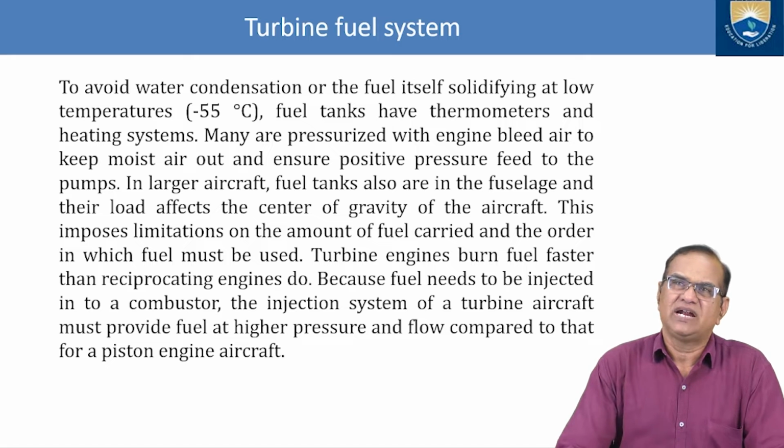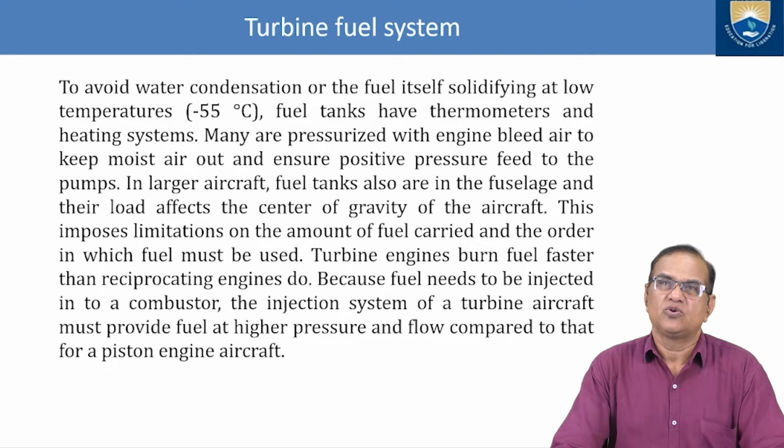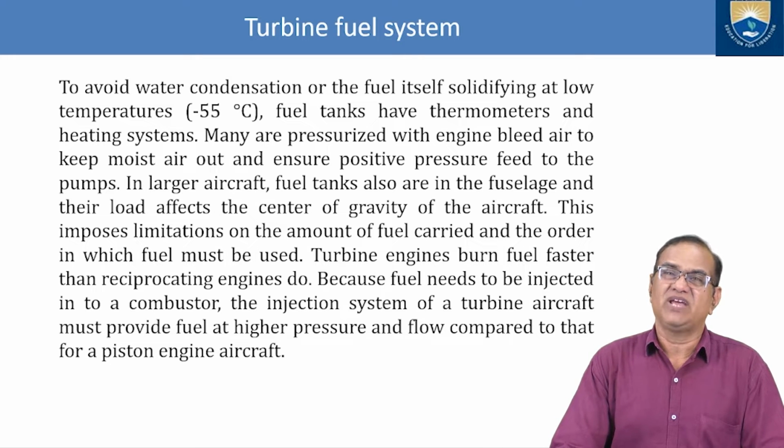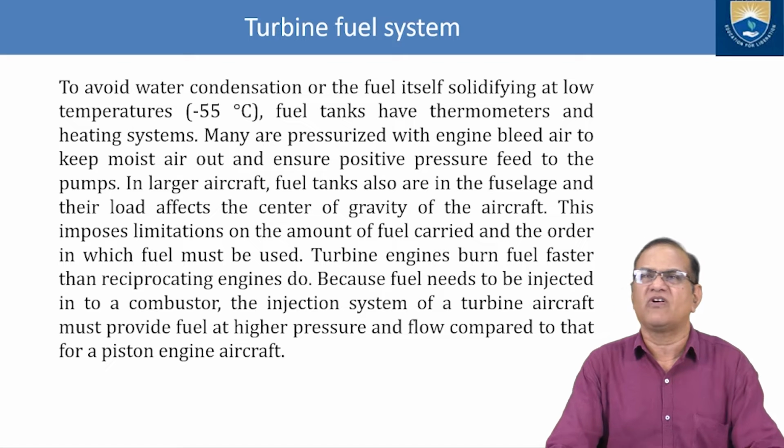Now I will talk about the turbine fuel system. Between piston and turbine, there is a minor difference in the system. To avoid water condensation or the fuel itself solidifying at low temperature, minus 55 degrees centigrade. If you are flying the aircraft at a very low temperature, like Siberia, Antarctica and some other places, the temperature is very, very low. So there is a chance that the water which is mixed in the fuel, sometimes due to atmospheric conditions, is going to freeze, and this will cause a lot of problems for the system.